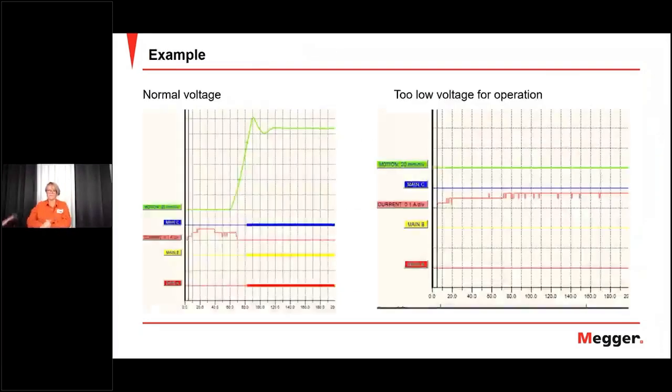Here we have a little measurement on a breaker with a very low current. So the coil current, the red one here, is not looking so very good. But this is the normal operation for the circuit breaker. But to the right, we have tried to operate with a lower voltage, and it was not enough voltage for operation. So this breaker was not in such a good shape. So it never moved, the motion never changed, and the current didn't show the normal trace, and we didn't get any timing trace.